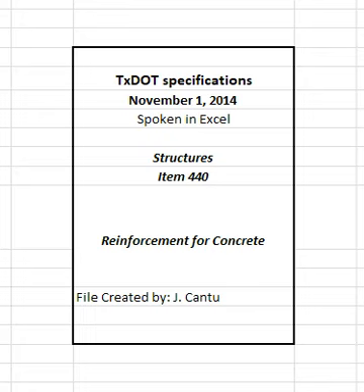2.1 Approved mills. Before furnishing steel, producing mills of reinforcing steel for the department must be pre-approved in accordance with DMS 7320, Qualification Procedure for Reinforcing Steel Producing Mills, by the Construction Division. The department's MPL has a list of approved producing mills. Reinforcing steel obtained from unapproved sources will not be accepted.